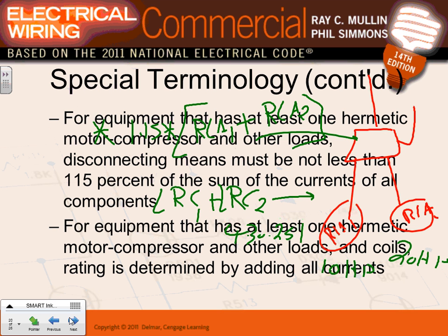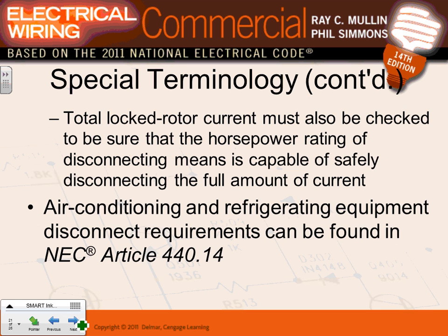You take the two locked rotor currents, add them up, and size the disconnect to carry them. I will have a calculation for you in the spring. I just don't do the calculation now. We will do calculations in the spring, guys, on how to size them. If you know it now from the book, great. Really, no rocket science. You take the locked rotor current here plus this, go to the table, size your conductors, and size your disconnect horsepower-wise.